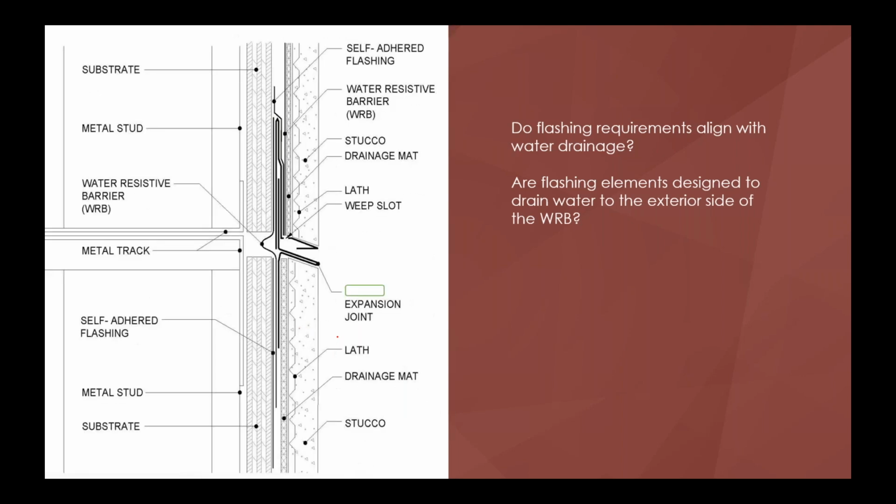What about when it comes to an expansion joint? We want to do the same thing. Now you notice there's no sealant in here. We don't want to have sealant in there because when this comes out, I'm dropping water right here. I want that water to be able to get out. So we don't really want any sealant on an expansion joint.